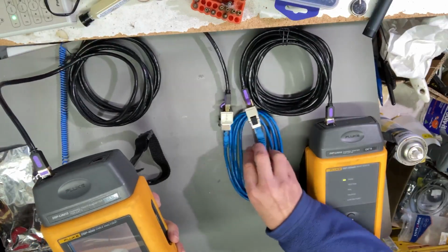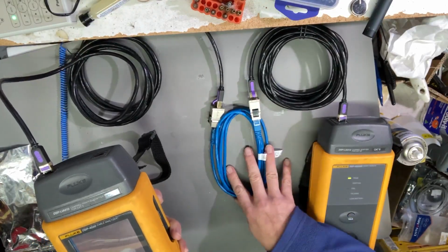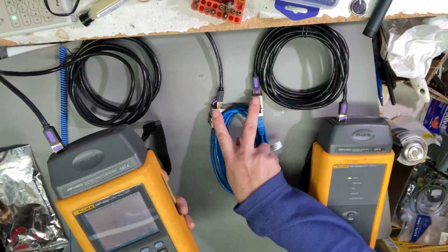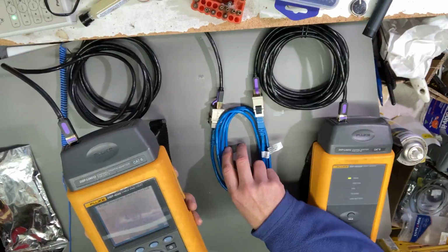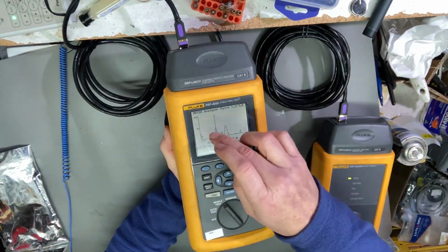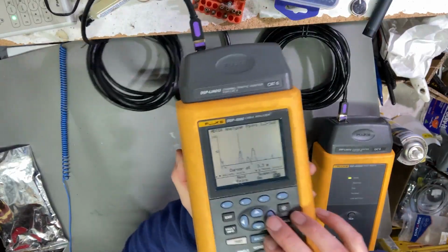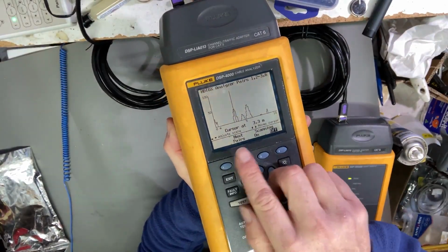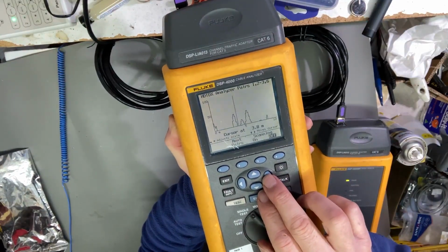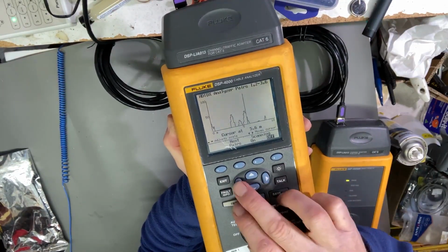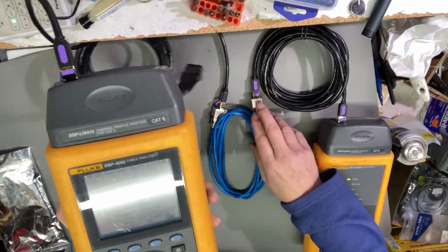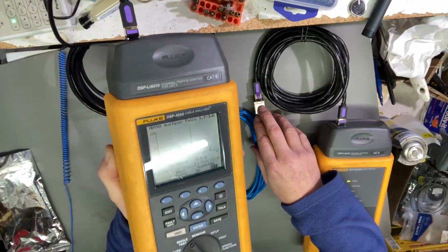Then I've got quite a long cable which doesn't even meet Cat 5. It says it meets Cat 5, but doesn't. Notice there's 2 connectors here, these couplers. We're getting reflections off those couplers, and that line with the cursor at the moment is that first coupler. That other line there, that's this coupler here. So we can actually see, it is truly like a map of the cable.